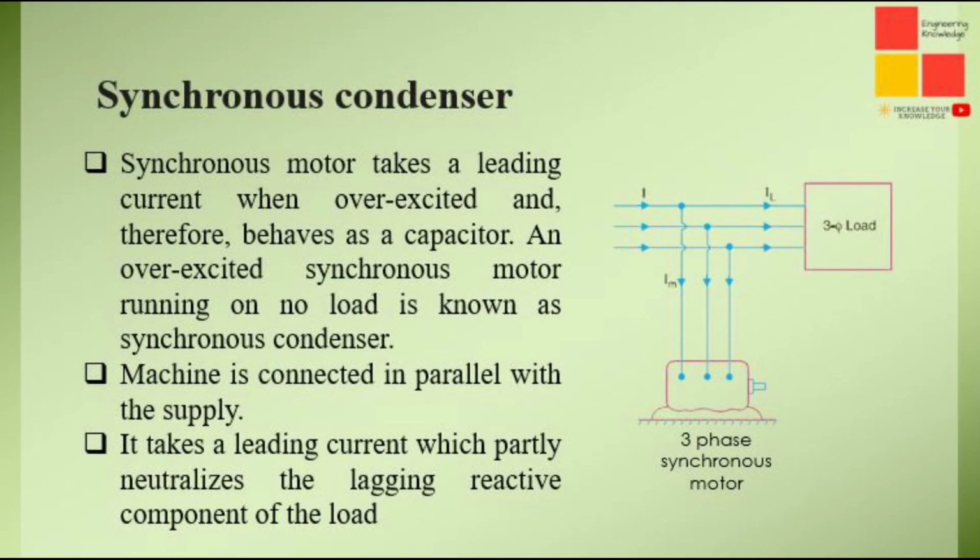The synchronous condenser can be defined as follows. A synchronous motor takes a leading current when overexcited and, therefore, behaves as a capacitor. An overexcited synchronous motor running on no load is known as a synchronous condenser. The machine is connected in parallel with the supply. It takes a leading current which partly neutralizes the lagging reactive component of the load.